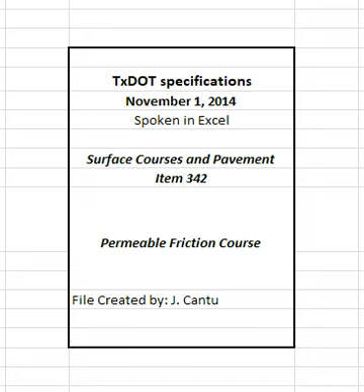Use a handheld thermal camera or infrared thermometer, when a thermal imaging system is not used, to measure and record the internal temperature of the mixture as discharged from the truck or material transfer device, MTD, before or as the mix enters the paver and an approximate station number or GPS coordinates on each ticket. Calculate the daily yield and cumulative yield for the specified lift and provide to the engineer at the end of paving operations for each day unless otherwise directed.